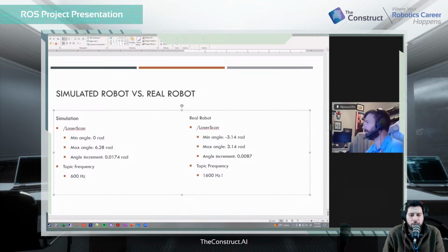If I was in a while loop, and within that while loop I was publishing velocities, it was publishing at 1600 hertz, and so I overloaded this bandwidth, and the robot is acting laggy. It'll tell me that it's aligned to the wall, but then it's still executing velocities in the rotations queue based on old information. I would go so far as to eliminate the queue entirely, just one queue size. It didn't work. With some help on the forum, we found out that it's really frequent publishing, and so if you put a timer into your callbacks, you can reduce this frequency and reduce the bandwidth on your robot.